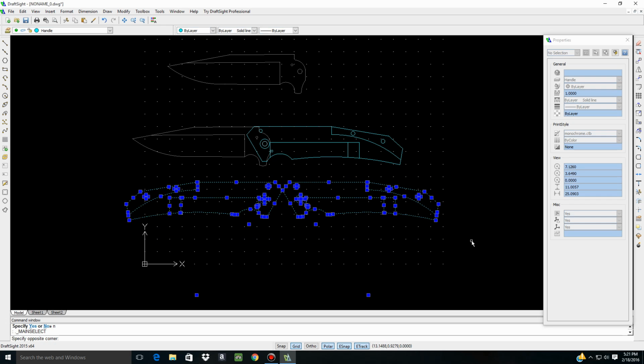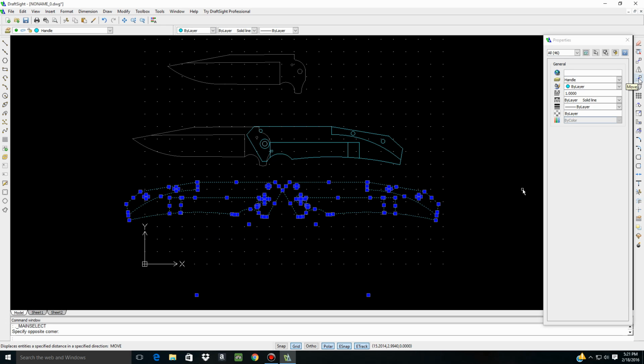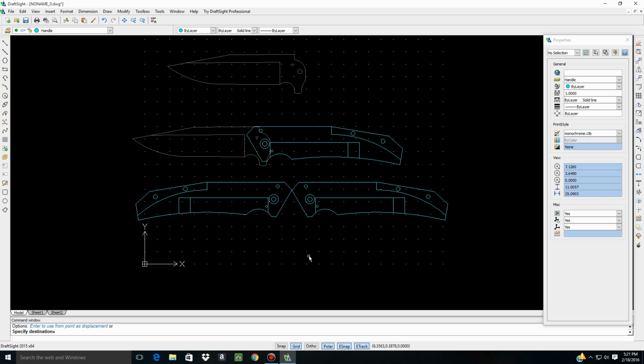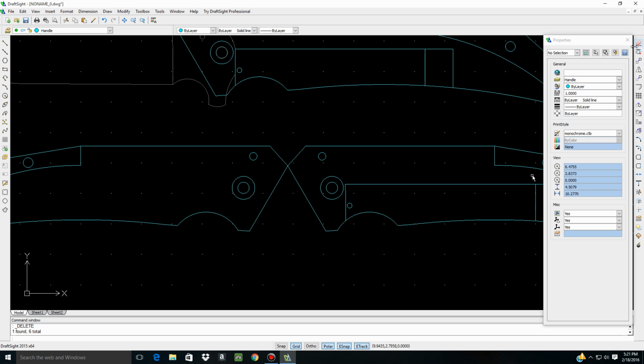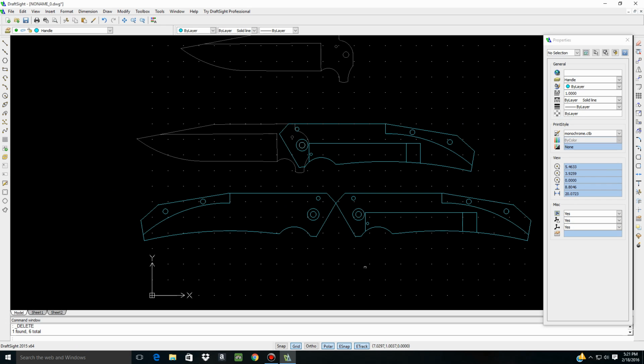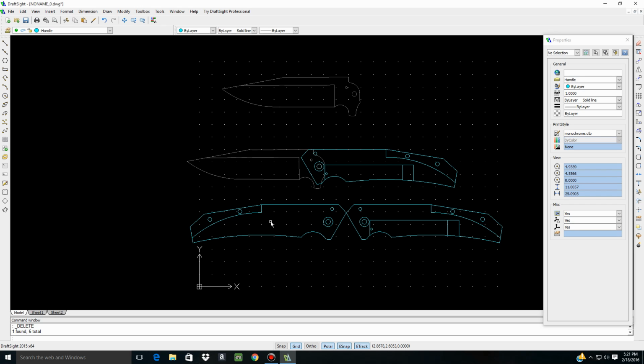Now this is a little off my page here, so I'm going to move it. For that, you just highlight it all, select move, and we'll grab it right there in the middle. You could separate these if you want to. Now, here's the thing. We don't need two lock sides. So what do you do? You go in one, select everything that makes it a lock side, and simply delete it. Okay, so now we have a lock side and a non-lock side.